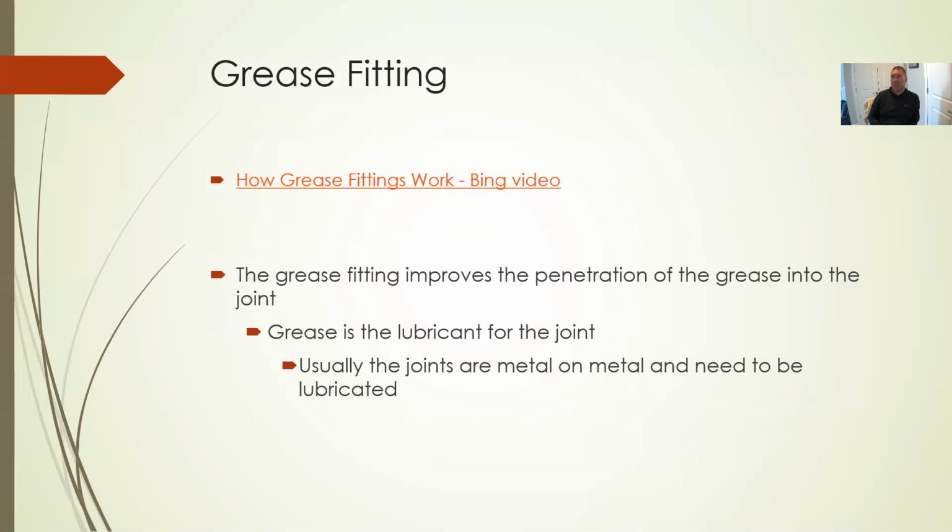If it's a piece of equipment that sat outside for 6 months, went through the hot and the cold, freezing, thawing, whatever the case is, the grease is in that joint. Still things can happen to that grease in that joint, right? So, need to do those things even when you're not using that piece of equipment, right? Same thing with your car, right? If you have a car that sits in the garage for 8 months, and you change the oil beforehand, well, that oil breaks down too, right?